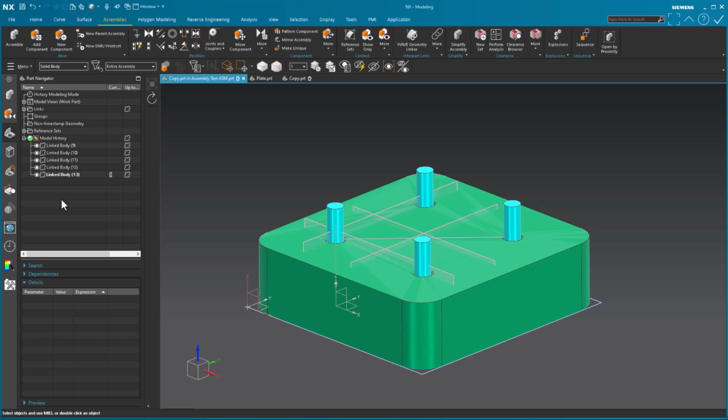I don't even want the opportunity for a link to potentially occur because of positioning, et cetera, et cetera. So maybe you don't want to add the part to the assembly and then delete the part out, because sometimes that can be weird and cause potential issues depending on what you're doing, because there may be links to other things.